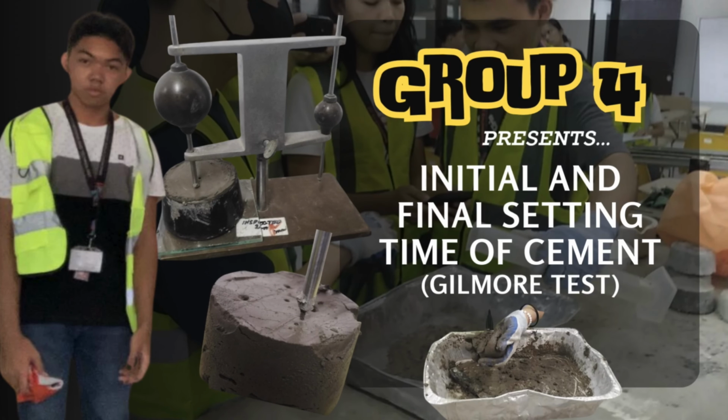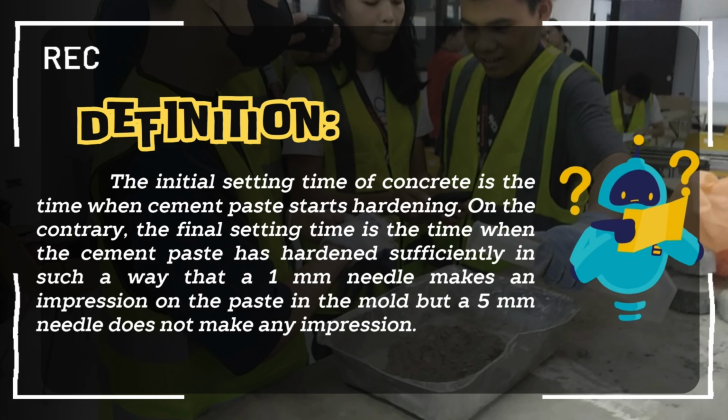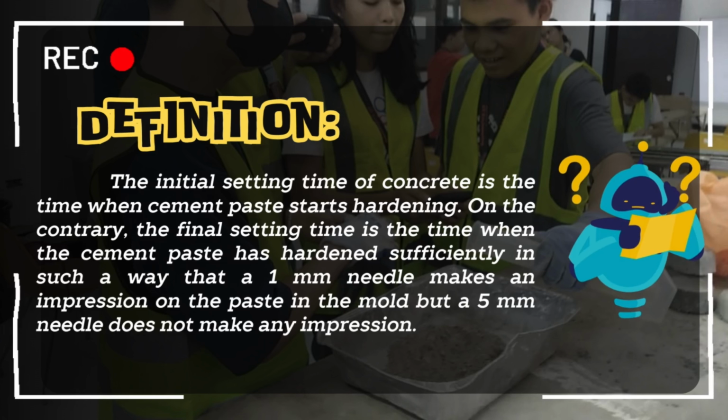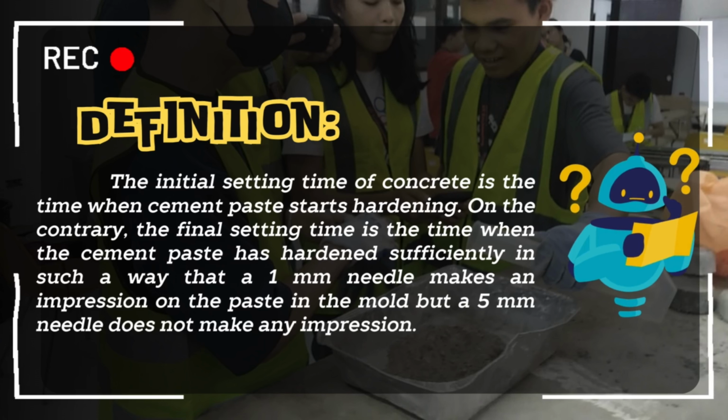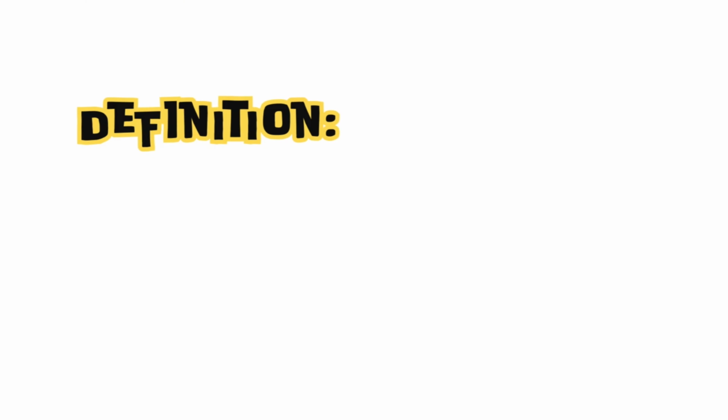Group 4 presents initial and final setting time of cement using the Gilmore test. The initial setting time of concrete is the time when cement paste starts hardening. On the contrary, the final setting time is the time when the cement paste has hardened sufficiently in such a way that a 1 mm needle makes an impression on the paste in the mold, but a 5 mm needle does not make any impression.